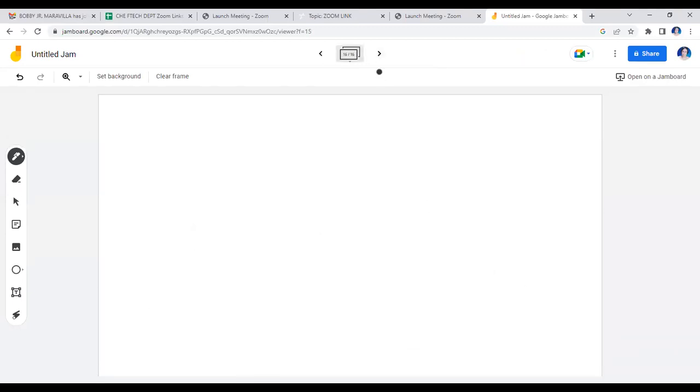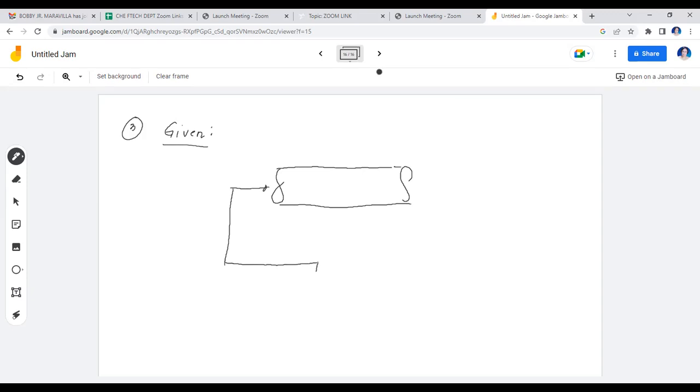So this is our third sample problem here. And of course, we need to write first what is given. So originally, you have a PFR. And then you're going to hook up to this one a CSTR. So it says in the problem that conversion is 96%. So whether it is only your PFR that is working, or both, the conversion in both streams when they're hooked in parallel should be the same.